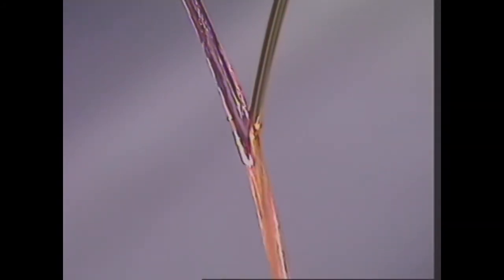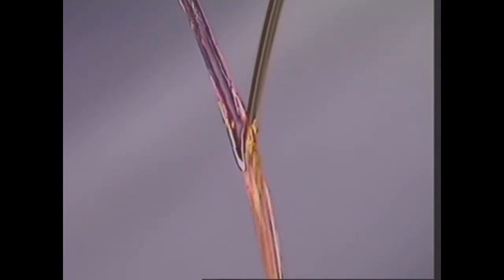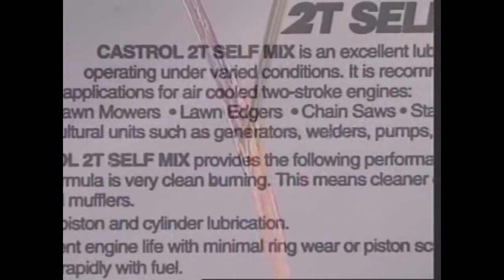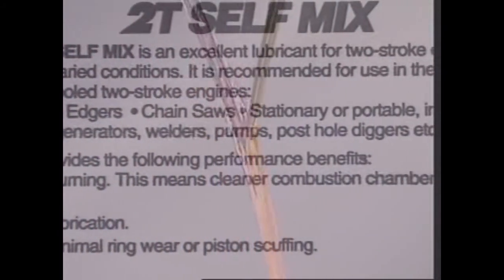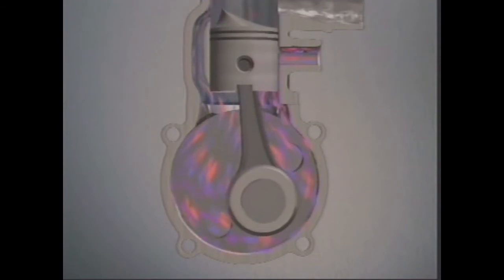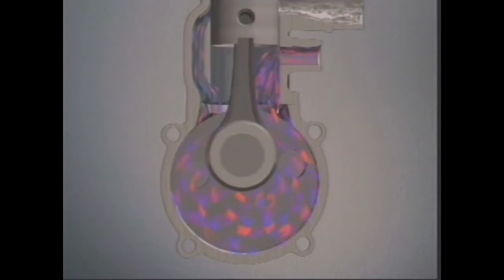In a two-stroke petrol engine, the oil and petrol are usually mixed before they enter the engine. Different engines use different ratios, as given in manufacturer's specifications. Oil, air and petrol enter the crankcase. The high temperatures vaporise the petrol and the oil lubricates the moving parts.